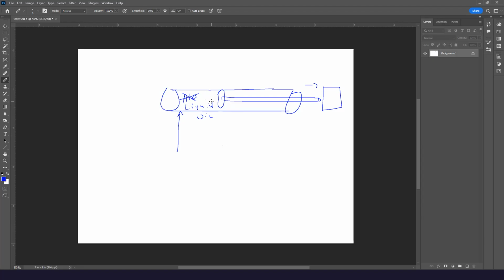It doesn't work well with transmitting large amounts of energy or force, because oil is incompressible. That pressure that you're going to control here, if we move the liquid into this chamber here, it doesn't compress. There are no negotiations. There is no spongy or springy type of action when we talk air or gases. When it's liquid, there is no compressibility. This thing moves, and if you don't want to be crushed, you better get out of the way.